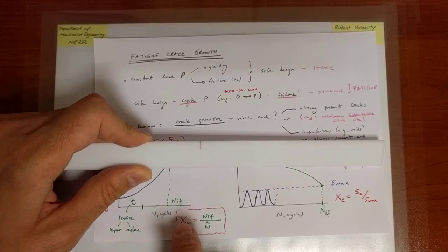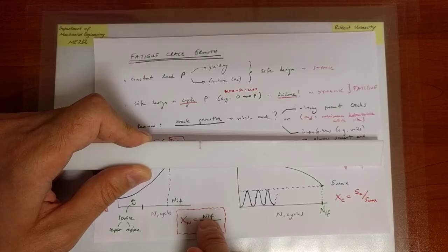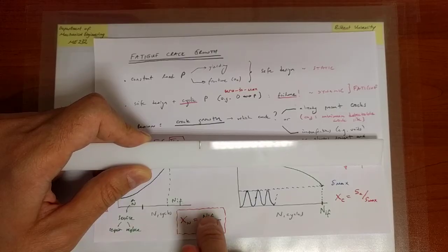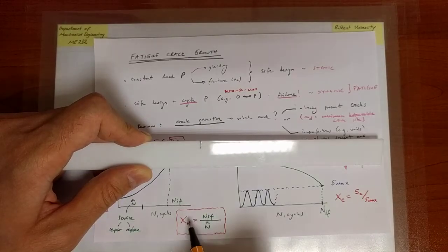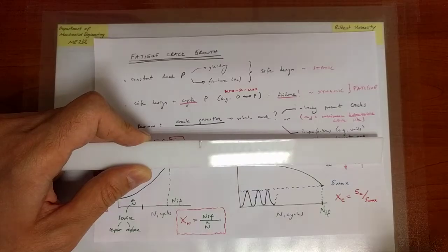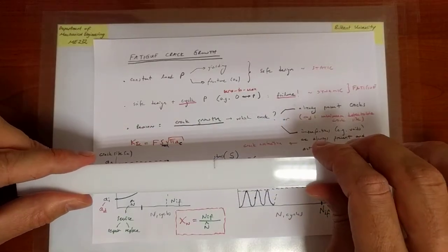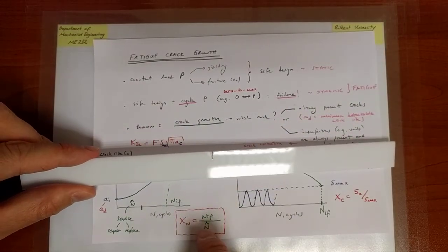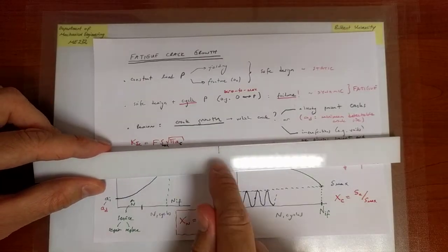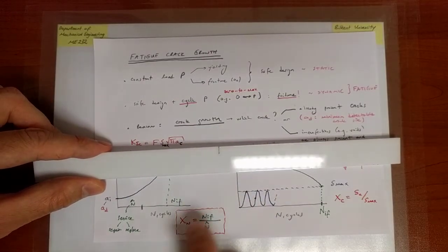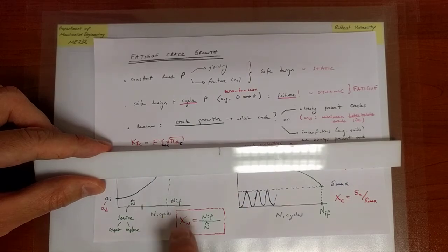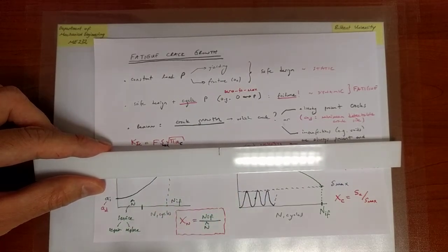Okay, so if I know the safety factor, and if I know the number of cycles it would take to failure, if I can somehow predict it or measure it, then I could calculate n hat. If I know this, and if I know that, I can calculate this. So then I can tell you, okay, are you going to use this piece in such and such application? Then you better service it with a safety factor of 10 after 100,000 cycles, because I know that experimentally or theoretically that it will actually fail after 1,000,000 cycles, right? So that's the practical outcome of that nice equation.